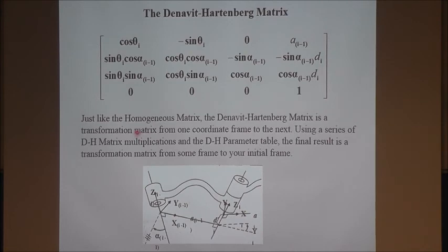So you now have two competing approaches. One is the combination of translation and rotational matrices, 4 by 4. The other one is the same transformation, but within the framework of new parameters, which are consistent in terms of definition and order, which one comes first, from one joint to another joint to another joint. Those are the DH parameters for every single joint. Okay? And as I said, they do come together in a table with your robot.